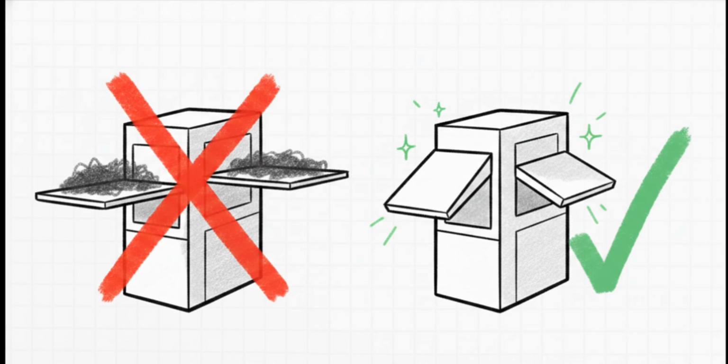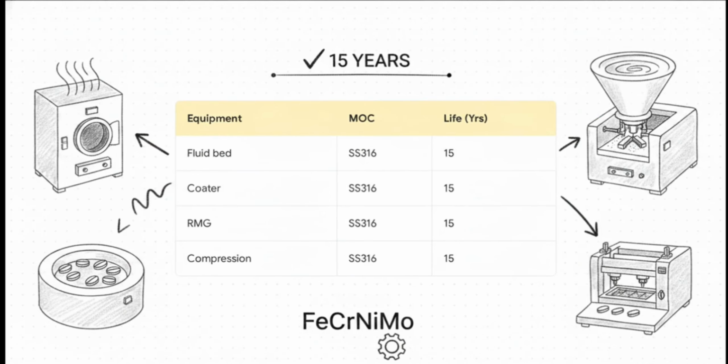The guidelines explicitly state that horizontal surfaces or ledges that accumulate particles have to be avoided on the machinery. Because OSD powder processes are inherently super dusty, a ledge on a piece of processing equipment is just as hazardous as a ledge on a wall. The equipment has to be designed for absolute ease of sterilization and simple aseptic setup. And this brilliantly illustrates that point.